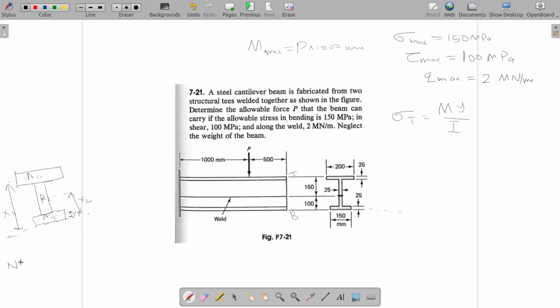So the location of the neutral axis, x centroid or xna, whatever you like to call it, will be sigma xi Ai divided by sigma Ai, that is A1 x1 plus A2 x2 plus A3 x3 divided by A1 plus A2 plus A3.